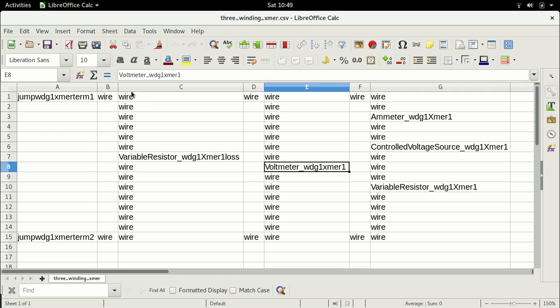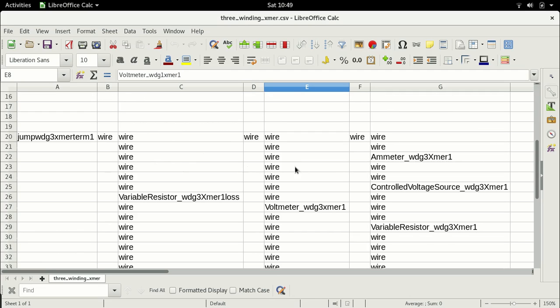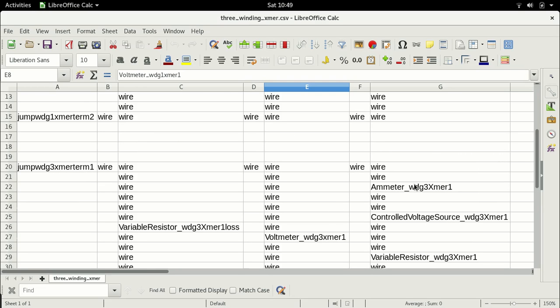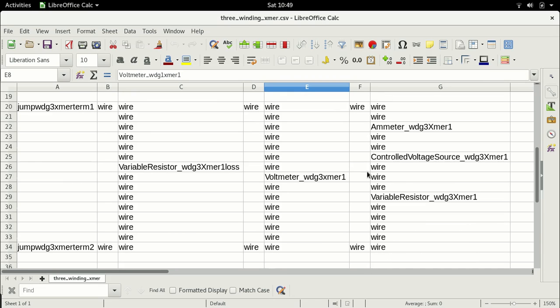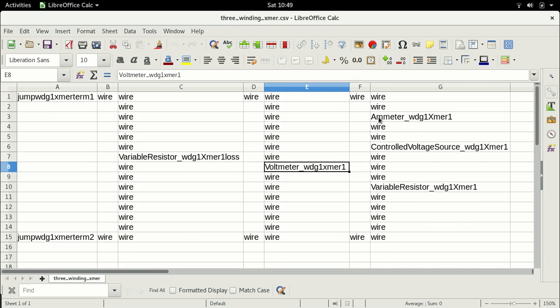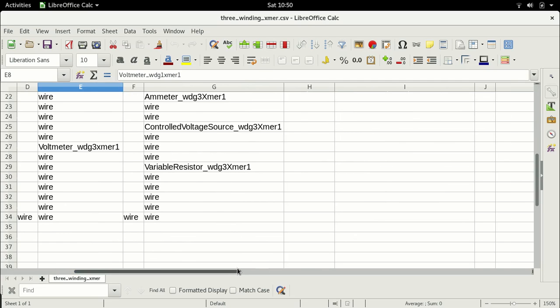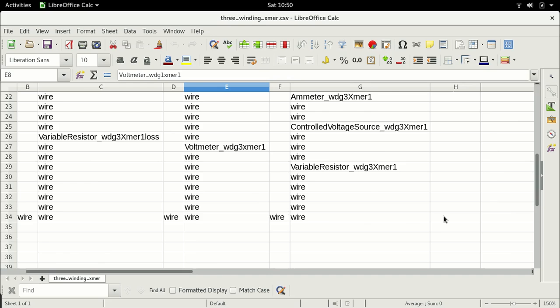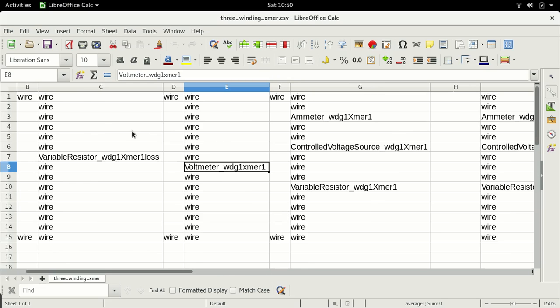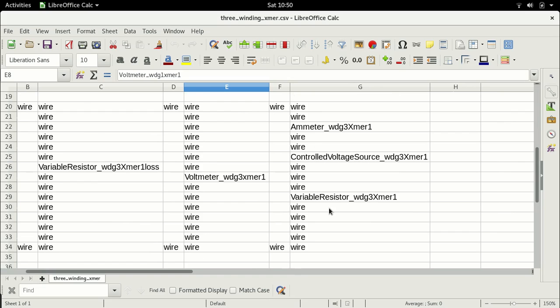So even if there is no input from the battery to winding 1 of the transformer, we have connected winding 3 to ensure that the current does not get disturbed. So this winding 3 now acts as a freewheeling path. As you already know, winding 3 has a dot polarity that is reverse to winding 1 and winding 2. In the case of winding 1 and winding 2, the dot polarity is on the upper terminals, but in the case of winding 3, the dot polarity is at the bottom terminal. So when the switch is off, this winding now supplies current back to the DC input.